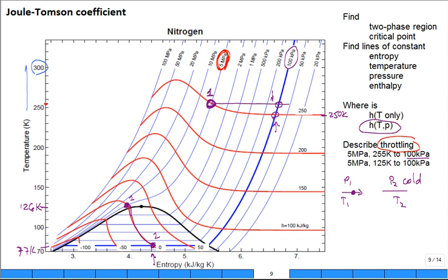Put a turbine in, right? What's the turbine going to do? It's going to convert some of that flow energy or enthalpy into some shaft work going out, and I'll do something else with that shaft work. I'll hopefully do something good with it, but as long as I get it out of the nitrogen, right? So if I put in, let's say, a turbo expander right here, here's my illustration of a turbo expander, I'm going to extract some power out.